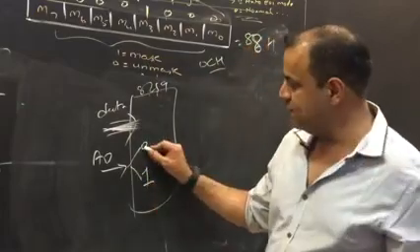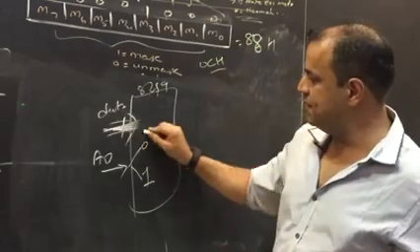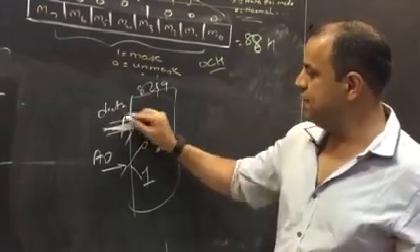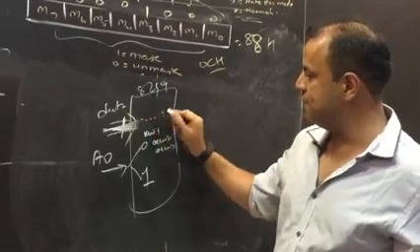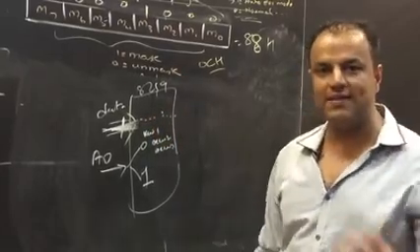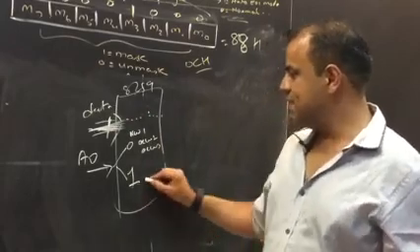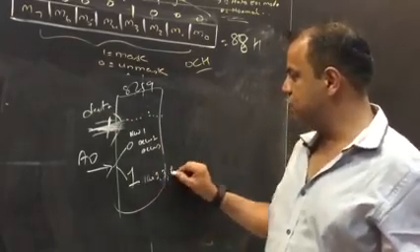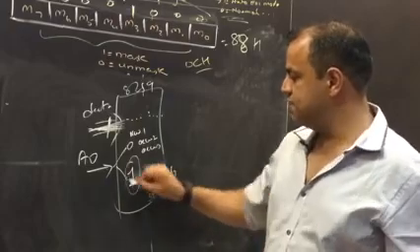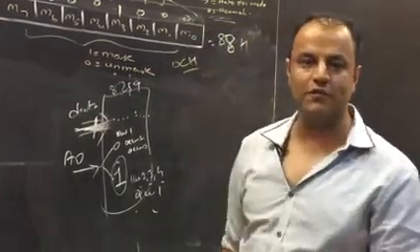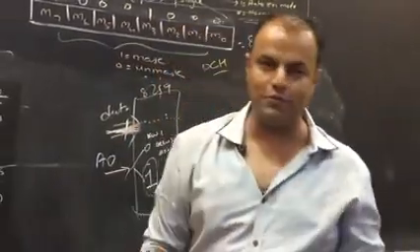So whenever A0 is 0, the command over here can be either ICW1, OCW2 or OCW3. For that, it will look at the fourth and the fifth bit of the command and will understand and interpret the command in that way. If A0 is 1, then the command can be ICW2, 3, 4 or OCW1, which it will identify by the sequence in which they have occurred. Please tell me, are you clear? So that's the role of A0, to identify the commands within 8259.